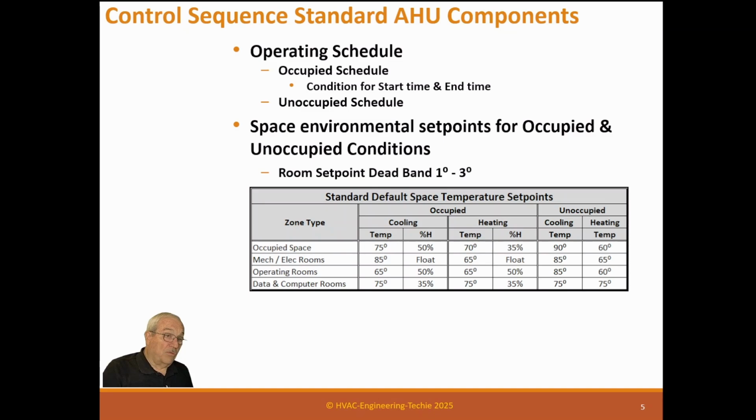Or if it's 84, then you compare those two until you see which is the most energy efficient. If it takes less energy to pull that building down from 90 degrees to 75 degrees than it does to keep it at 85 degrees, and to pull down from that, then you make your decision on that. Unfortunately, it's hard to make a rule of thumb judgment because every building is different.